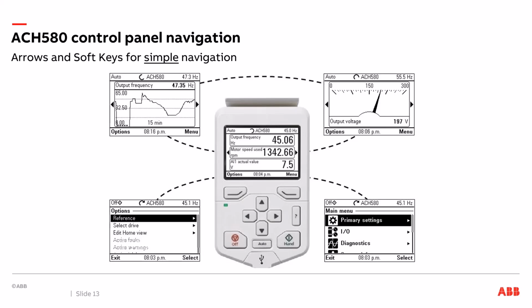If I've got a really advanced building automation system, when I say advanced, I mean really well integrated into the drive, a lot of times I can see these things through the automation system if it's trending the things at the frequency I want. But a lot of times, unfortunately, they're not fully integrated to that level. So you've almost got a little mini building automation system right in the drive. So you can do things like trend data over time, which can be beneficial for troubleshooting.